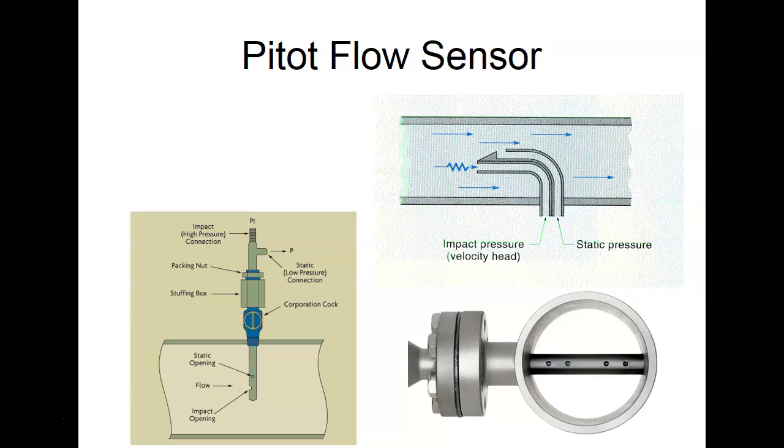So if you ever looked at an airplane, if you started walking down the sides, you'd see little holes on the side of the airplane. And that would be where you do the static at. And then on the front of the plane, you'd see these two pitot tubes sticking out. Our pitot tubes were heated because our plane could fly at 32,000 feet, and the pitot tubes would actually freeze up, so they were heated.